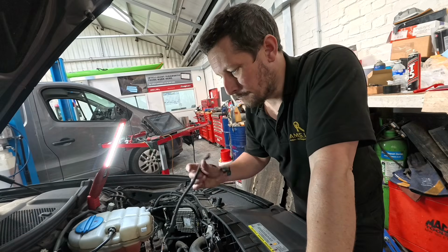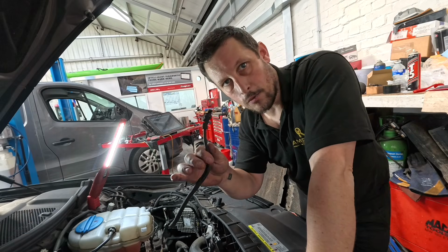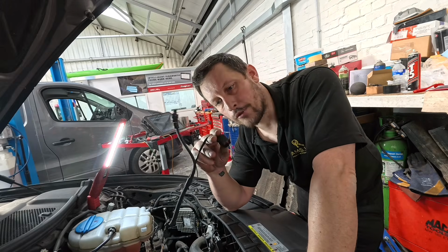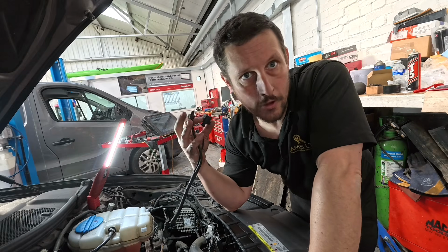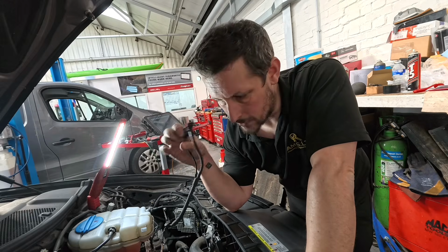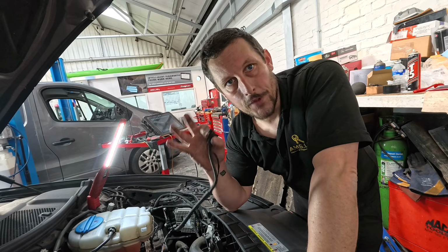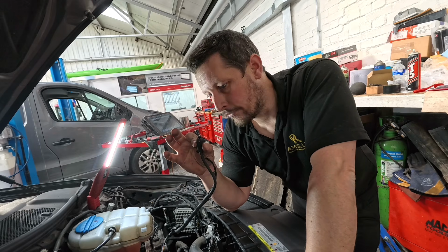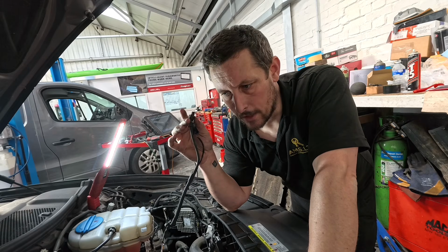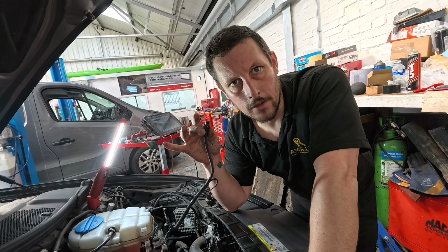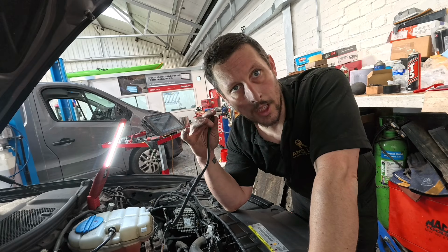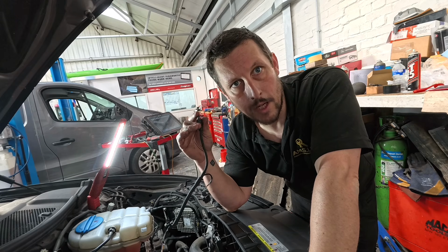So with a little bit of kicking and spitting, we've managed to get our wiring harness out, down to where the solenoid is. There were 3 wires running through that harness. The third wire goes to the LIN bus signal to the back of the alternator, so I've disconnected that for the purpose of testing. So we're going to get our AES Wave breakout kit of loveliness, plug into the back of these, and run the test again with the scope, running it through a test light and see if we can see those signals coming back and forwards.